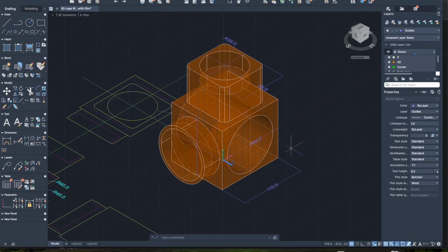Like I said, it would probably take a few attempts to get the dimension placed in the right spot. And then we have this side over here. So once again, you type in UCS, and this time we'll orient it over. Now, if yours is snapping inside the circle, and you can't go from this area over to here, because then when you pull your dimension, your numbers are reversed. So you always go left to right.